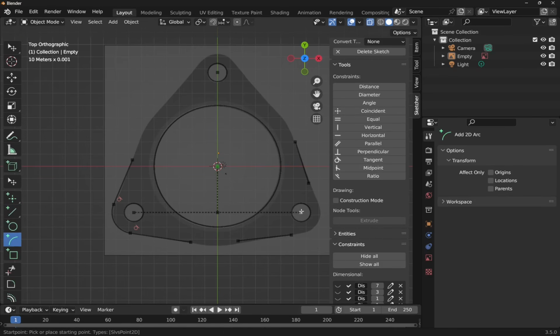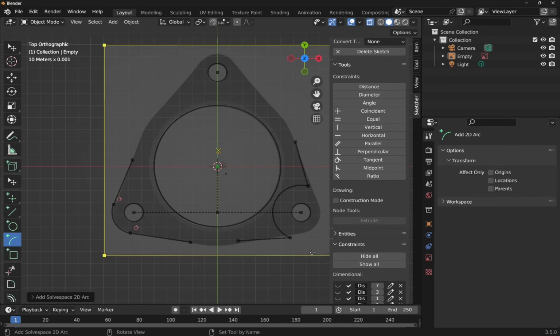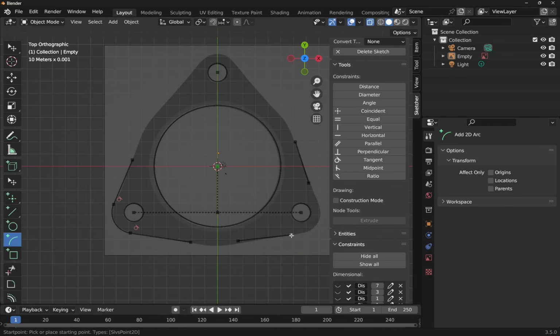Remember, it's a center point first, beginning point, and you can see what happens if we try to do that. That goes right away out here. So let's connect up to this point, and it's gone this way. Control Z that, because I don't want it that way. So we have to be wary when we bring these lines in of where they're going to sit. So center point first, I'm going to click on this point and just make an arc to about here, and we'll sort this out in a minute.